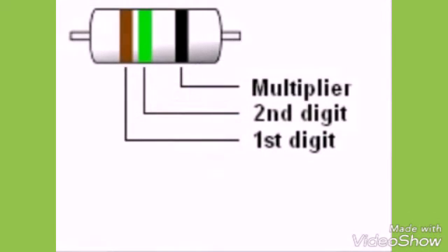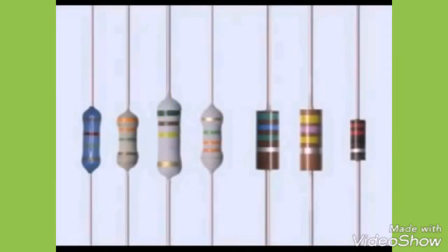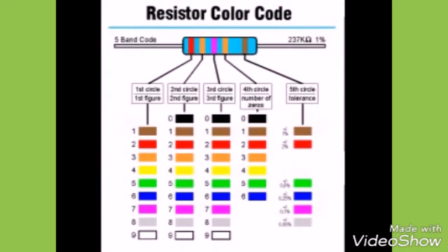Not all resistors have a 10 or 5% tolerance band. Many years ago, some resistors had a 20% tolerance, which was indicated by not having a fourth color band. You might find a 3-band resistor in an antique radio or television. For most applications, 5% or 10% resistors are more than adequate, but for some requirements a more precise resistor must be used. Precision resistors commonly use a 5-band color code.